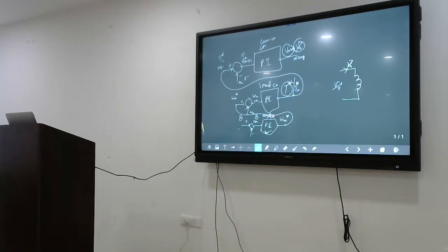If students are working effectively, the inner loop, where torque is nothing but the inner loop, is there inside. Outside, position controller is there. After that, speed controller is there. After that, torque controller is there. But in order to rectify the position error or speed error, your torque controller should work effectively. First, the torque controller should act first.